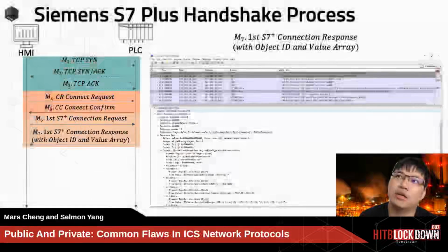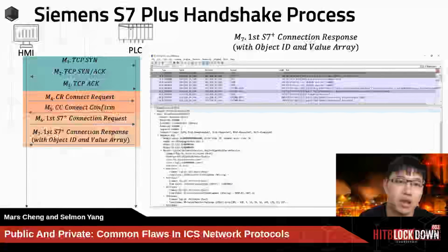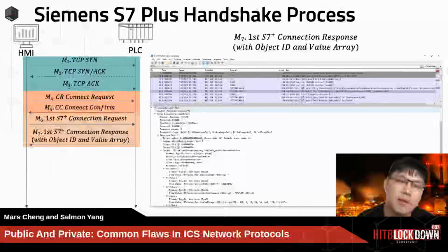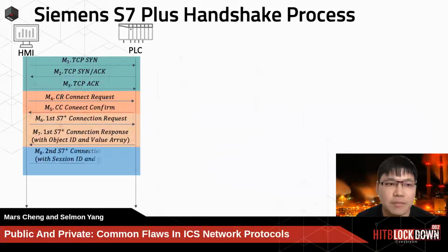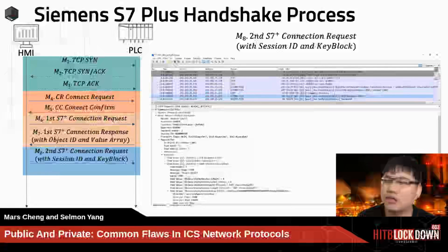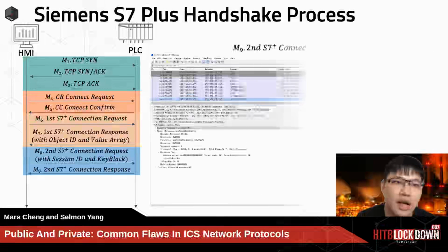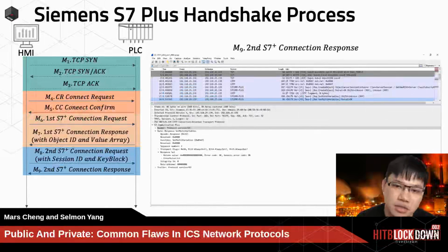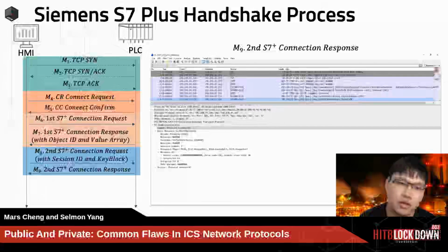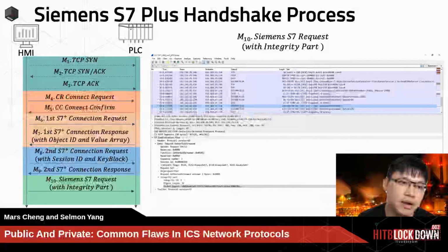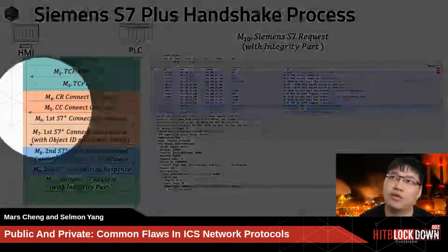So in here, still not real transmission of S7 Plus protocol data, but after message 7, they will do this connection request with session ID and key block, and send it, and get a response. And at this moment, they will actually do the encryption handshake. So they will do a real S7 Plus request with the integrity part.